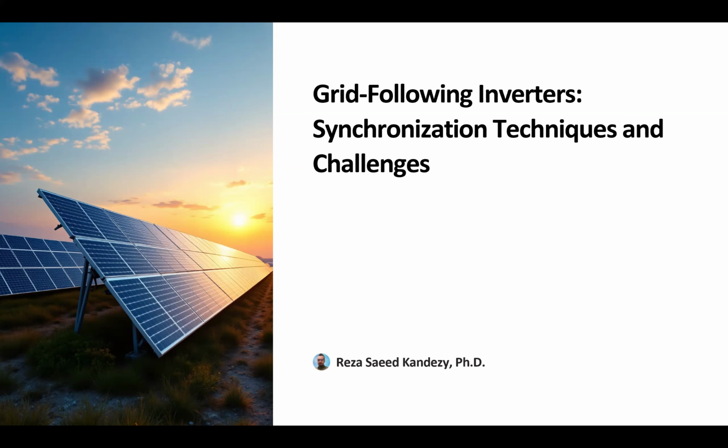We went through the THD analysis and we learned what power quality and harmonic distortion mean and how we could calculate that, and what the techniques are to mitigate those harmonics: either the software technique that we talked about for enhancing or optimizing the switching, and the hardware technique like passive filters that we talked about in our course.